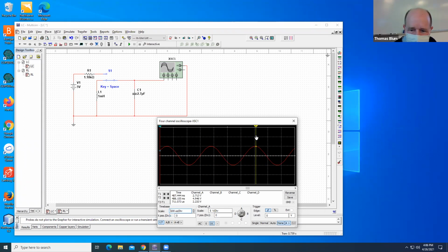And you still play the same game. You go from a high to the next high. So I'm high again, and that was 328.720 microseconds is the period. The period is the number of seconds for one cycle. So it is seconds per cycle. A frequency is a number of cycles per second. And so to go from a period to a frequency, you take the reciprocal.